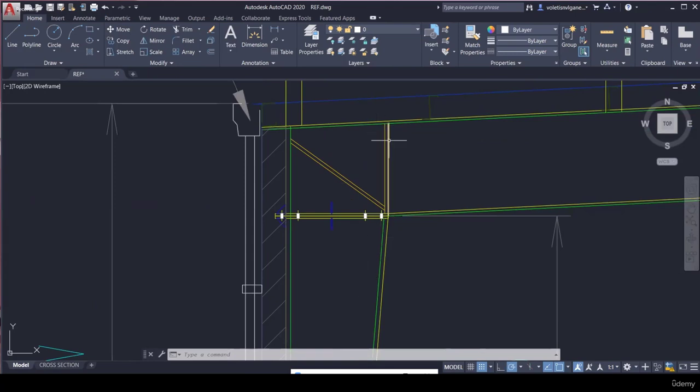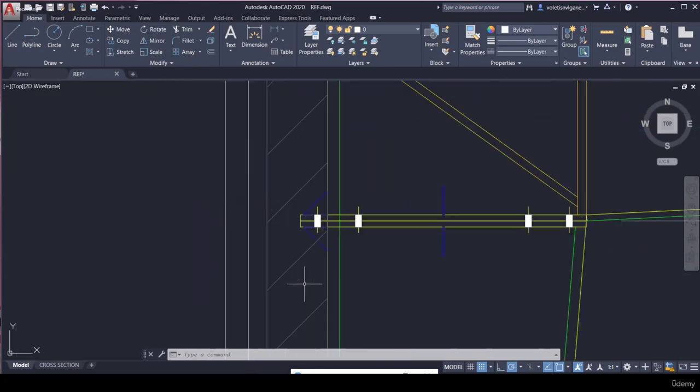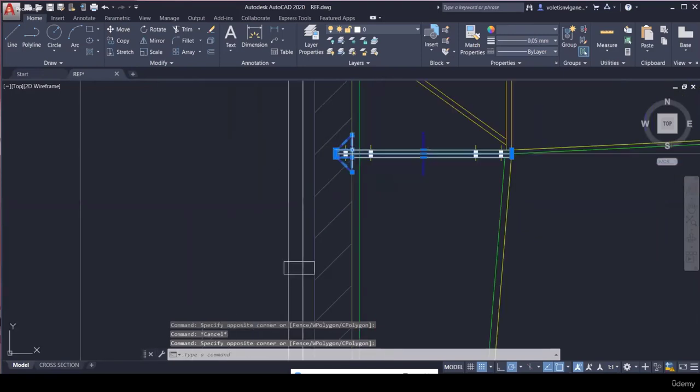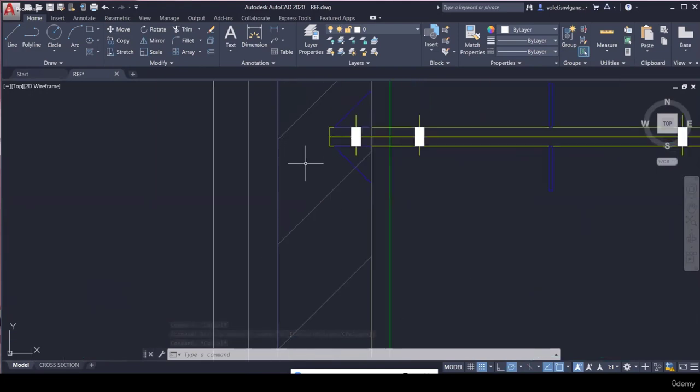Suppose this rafter depth is 500 and you got the connection as 600. You have to take the center line in AutoCAD and offset 300 above and 300 below only. For horizontal splice also, some portion extends beyond the flange, so no problem at all. Is this what you are asking?